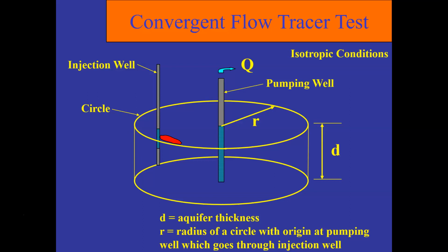And then it also has an orientation, a direction, if you're looking at an areal anisotropy. And in a vertical anisotropy, you're looking along a cross section, and there's a direction there. And it's usually the K max direction will be parallel to the bedding, being controlled by whichever layer has the highest hydraulic conductivity. And normally the lowest hydraulic conductivity is in the direction orthogonal to the bedding. Does that answer the question?